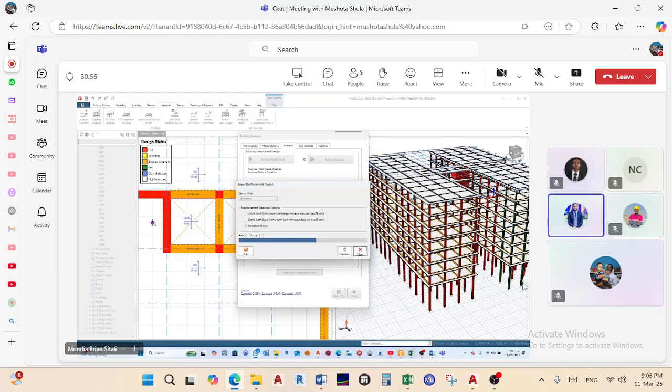If you have like 40 stirrups in a column, it will draw them as lines. So we cannot detail them like that. Columns have to be detailed differently. So it asks for extra work in detailing columns, and it also doesn't show the foundation, so you have to manually detail that one.